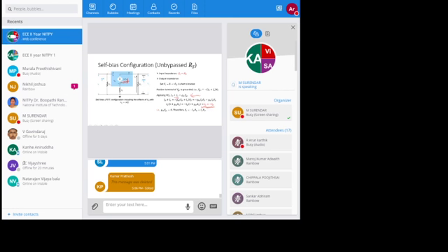Therefore we get the output voltage as minus ID into RD. Finally, the output impedance is the output voltage divided by the output current, which is nothing but only the resistance RD.